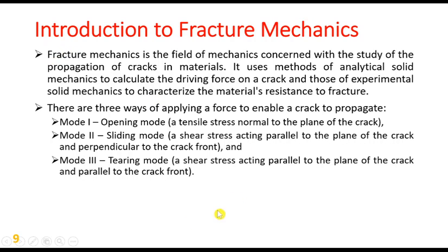According to this Wikipedia content, fracture mechanics is the field of mechanics concerned with the study of the propagation of cracks in materials. As I said, it uses methods of analytical solid mechanics to calculate the driving force on a crack and those of experimental solid mechanics to characterize the material's resistance to fracture. There are three ways of applying force to enable a crack to propagate. Mode 1, opening mode: a tensile stress normal to the plane of the crack will open the crack.